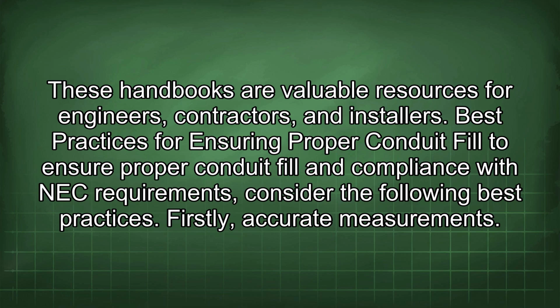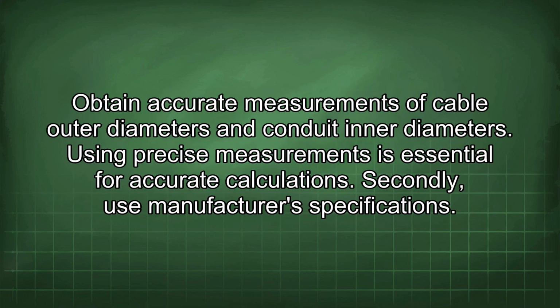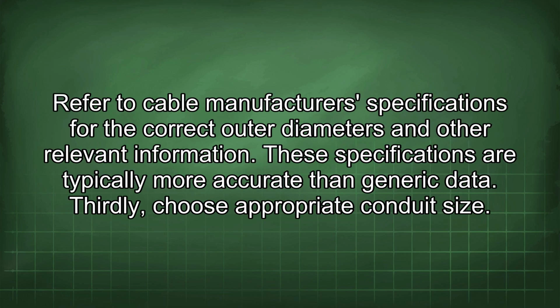Best practices for ensuring proper conduit fill. To ensure proper conduit fill and compliance with NEC requirements, consider the following best practices. Firstly, accurate measurements. Obtain accurate measurements of cable outer diameters and conduit inner diameters. Using precise measurements is essential for accurate calculations. Secondly, use manufacturer's specifications. Refer to cable manufacturer's specifications for the correct outer diameters and other relevant information. These specifications are typically more accurate than generic data.